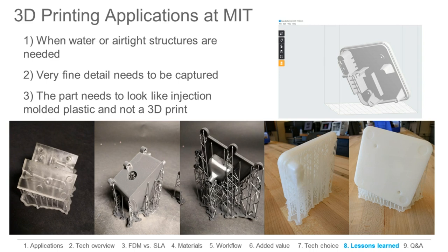And that brings up another good point, which is that whatever you print off of your printer doesn't have to be the final part. For example, another fellow was getting married last summer, and he wanted to do a cast bell for his wedding. As part of the wedding ceremony, they had a big fire and they did iron casting. He printed the positive for it on our Form printer and did this little bell, which they then cast and rang. So the Form does not print metal, but you can use it to then cast metal with. So think about multi-step processes.